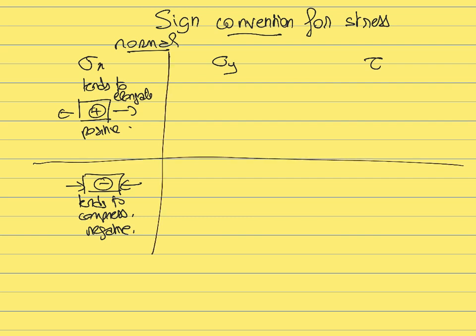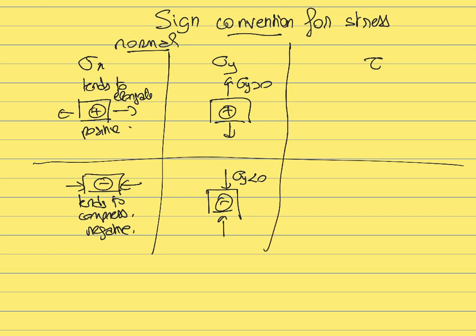Same thing for sigma y. We are going to use the same definition: if the stress is pointing towards the outside, then that's going to be a positive sigma y, and if the stress is pointing towards the inside, then that is going to be a negative sigma y. So that's going to be the negative convention for sigma y.